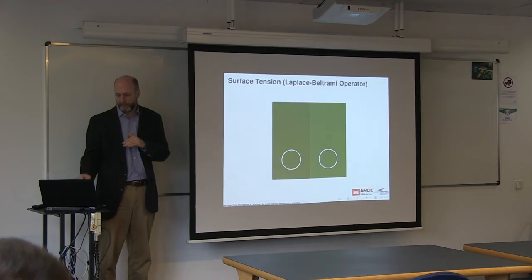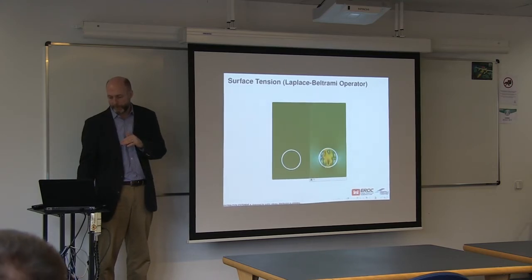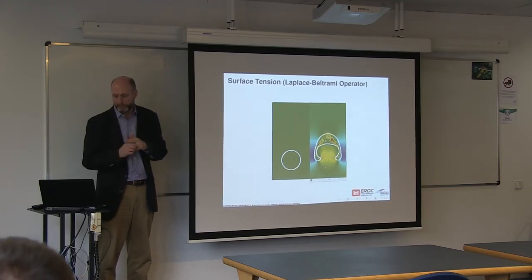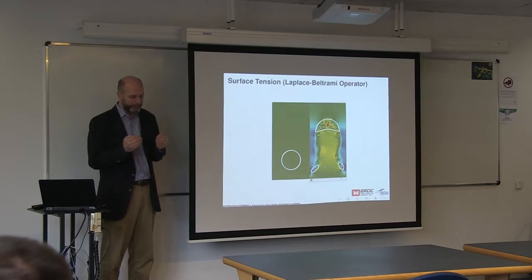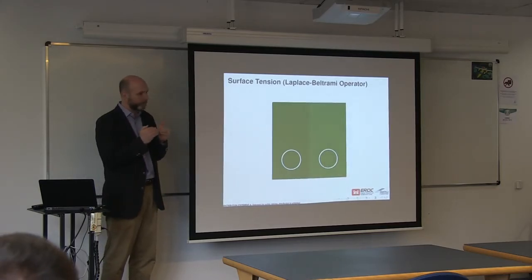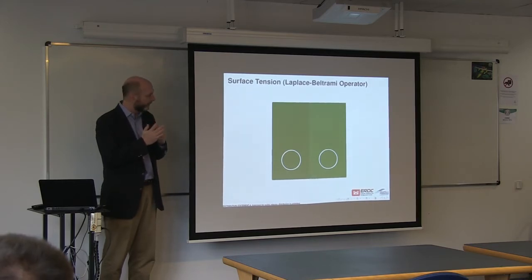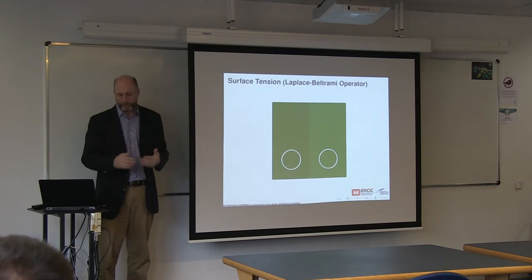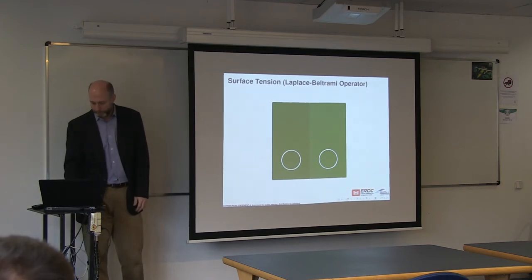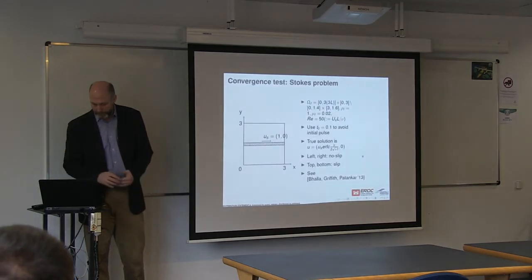We have good representation of the surface tension itself, in this case for a bubbly flow, but what we're lacking is the boundary conditions for the air-water interface as it intersects the solid phase. And there we need to do some additional work at looking at the dynamics of the contact line motion that we use in these models. So certainly if you have experience in that area, I'd love to talk to you because it's an area that is still, I've not seen a lot of work in that area.